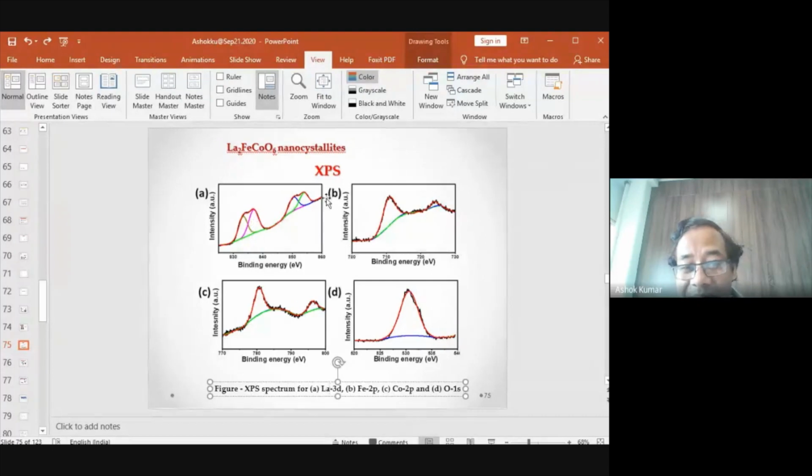Again I repeat, the surface becomes very important to study, because most of the properties are governed by the surface. And XPS is not giving bulk information. So if you do compound determination with the help of XPS and XRD, where XRD is a bulk technique, you may get different information, for example FeO by XPS and Fe3O4 by XRD. It is totally possible, because you should remember that the information given by XPS is on the surface, and XRD gives information from the bulk.